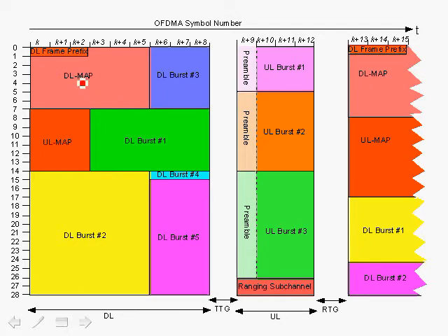The downlink map describes these regions, and for each region there'll be a data element describing it so that the particular subscriber can know all about this particular region: where it is in terms of the time slot and of course subchannel offset, the number of subchannels, and of course what the particular rate or coding is used to send the data here.